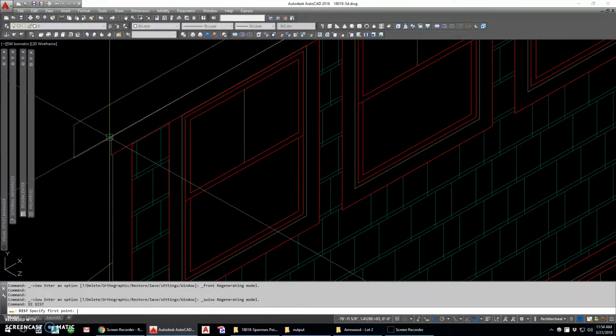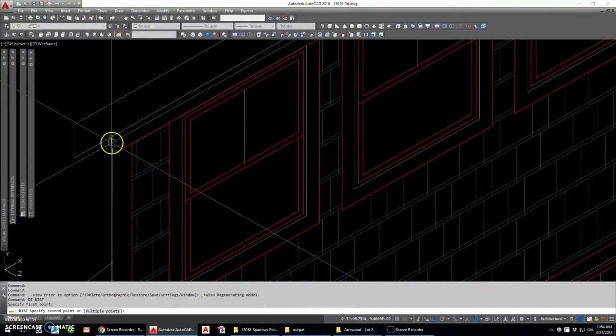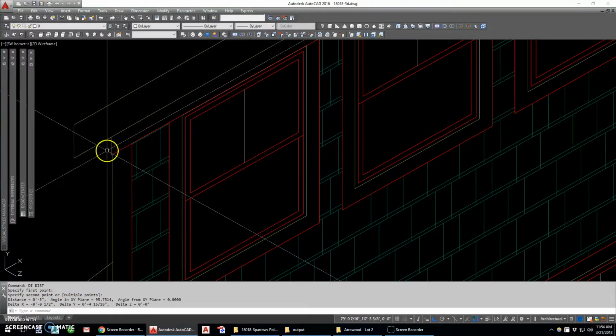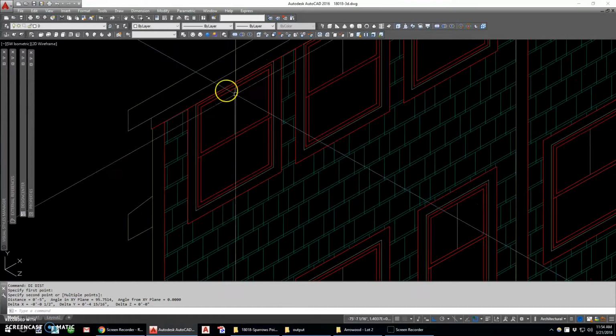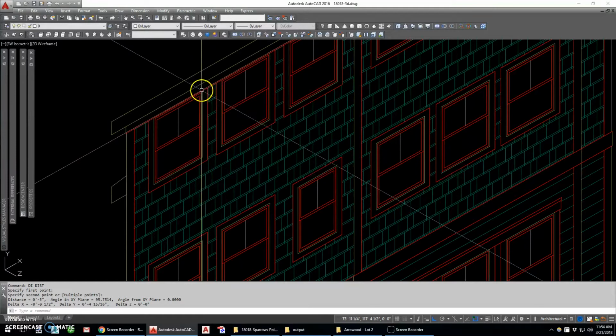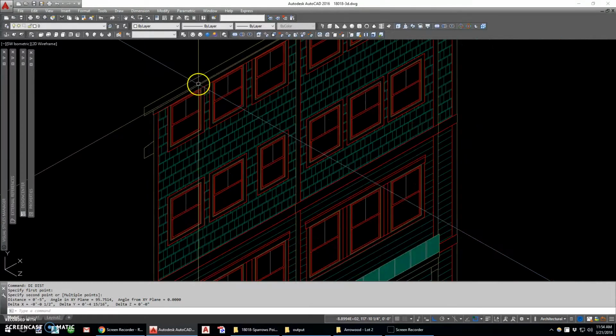This top board, I want it to project. Right now it's only projecting, if I do a distance here, a ½ inch from the house to the side. Typically this board wants to project at least an inch. That way I can project my other boards 3/4 inch to give myself a reveal line there for the rendering.